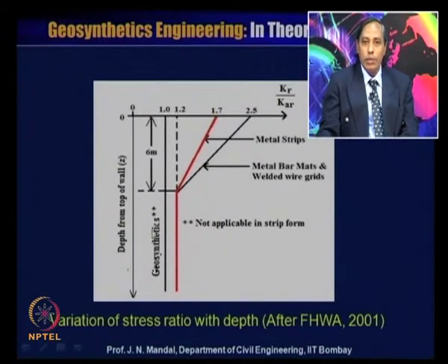This is not applicable in case of the strip for the geosynthetics material. For the geosynthetics material, K r by K a r will be equal to 1, that means K r will be K a r. So, you have to select this stress ratio K r by K a r based on the type of the inextensible reinforcing material.